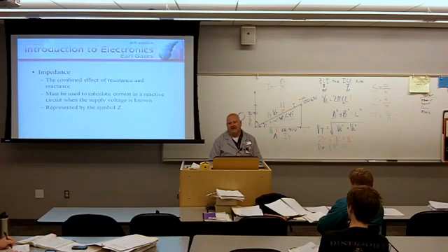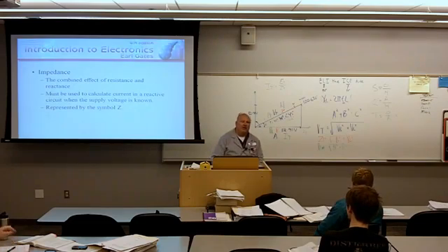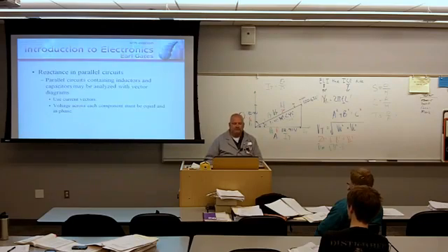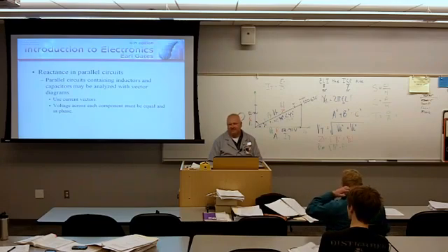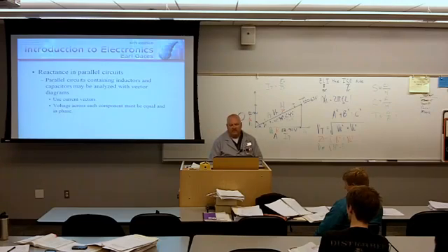Impedance, the combined effect of resistance and reactance, must be used to calculate out current in a reactive circuit when the supply voltage is known, represented by the capital letter Z. Reactance in parallel circuits. Parallel circuits containing inductors and capacitors may be analyzed with vector diagrams.